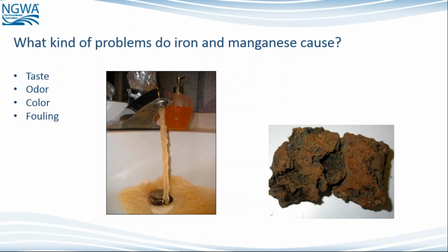As you can see here coming out of the sink, it's not very attractive from the aesthetic point of view, but certainly they can also cause taste issues, and in some problematic conditions, you may generate an odor, not so much from iron, but maybe some from a higher level of manganese and enveloped in various structures. I threw in the picture on the right, which is what we would call organically bound iron oxides.